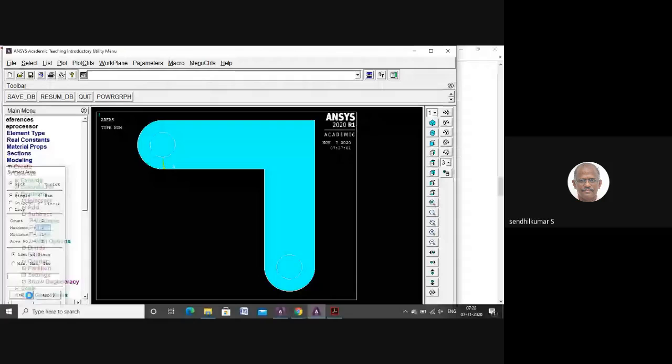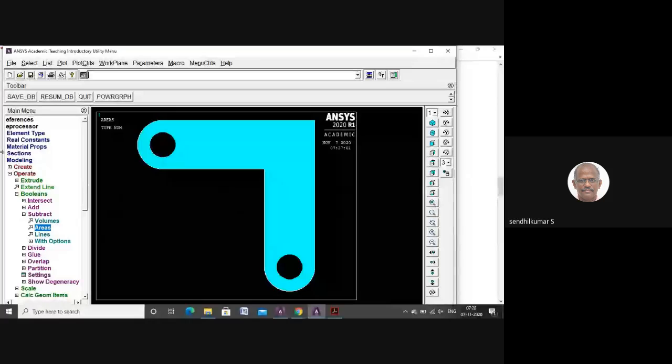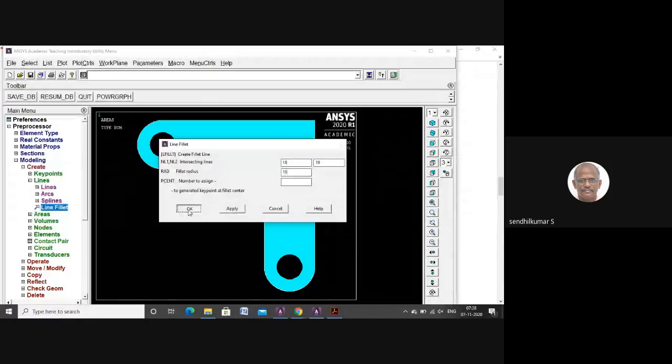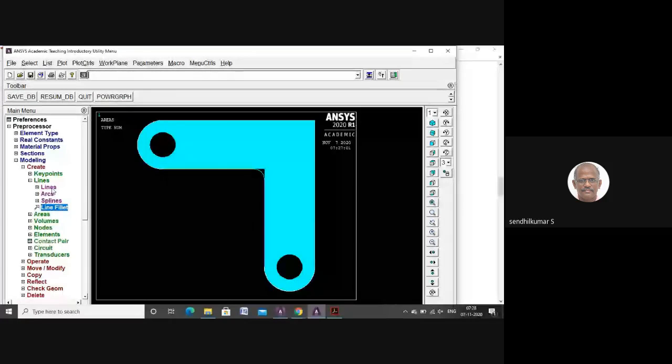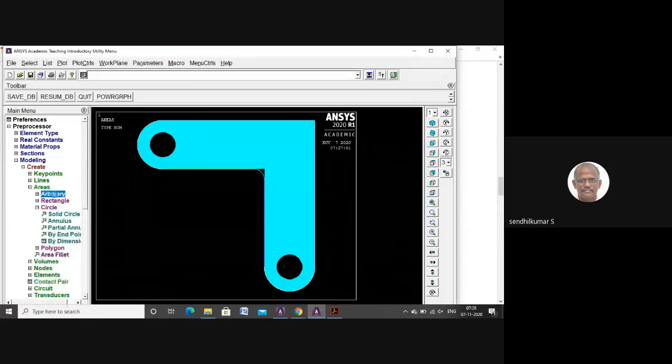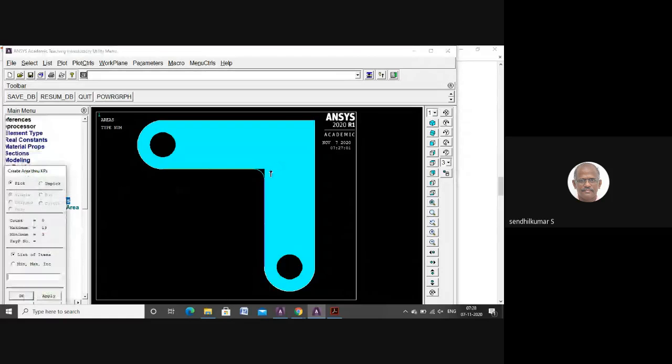Areas. Now after refreshing you can see that the areas are created and the entity will be modified. Now you can see a new modeled finite area has been created. Using a boolean operation only we completed all this task. Now since we do not need the sharp edges at these corners, we can create a fillet. So the fillet is being added.